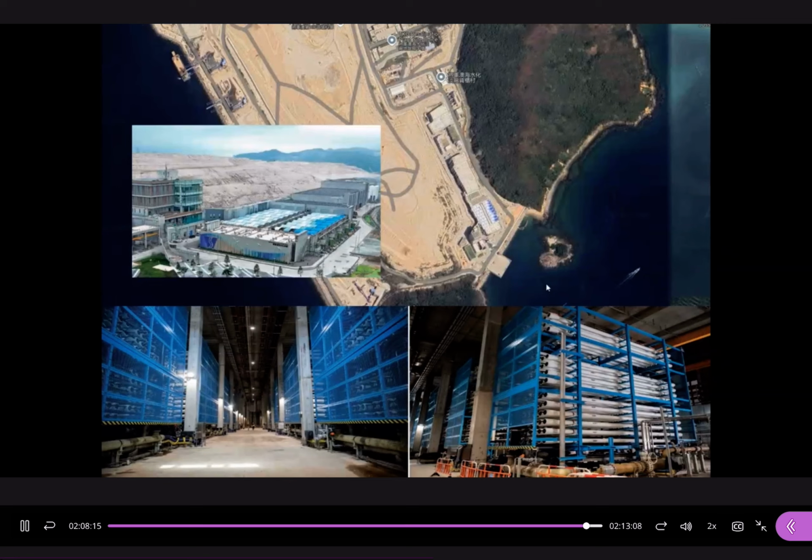DAF is exactly the reverse of sedimentation. In sedimentation, particles settle naturally to the bottom of the tank. But for DAF, air bubbles from the bottom bring the particles to the top water surface, and then all these substances are scraped off. This is used for substances with low density, because they are light, so it's more difficult to settle them than to float them. Perhaps our source seawater has more lighter materials, so DAF is used to remove these substances before sending them into RO.